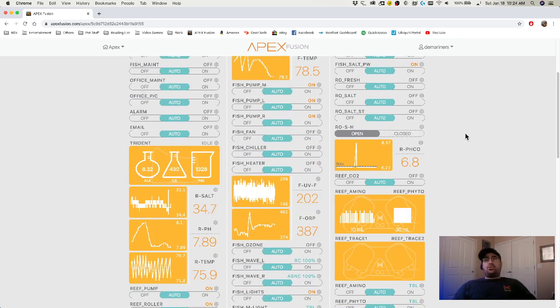That's basically saying to the Apex, I have power from the 12 volts. So generally what you'll do is you'll take the 12 volt, you'll plug that guy right into the power in the wall, and then you'll know if the Apex loses power. And the essential next step there is you'd have your EB8 or your EB4 or whatever unit you're using, and you'd plug that into a battery backup. So that way it enables the Apex to continue having power even though you've lost power. So that's how the power command works, and that's how the 12 volt power works. Does that make sense?